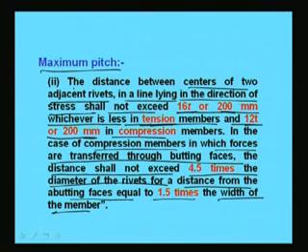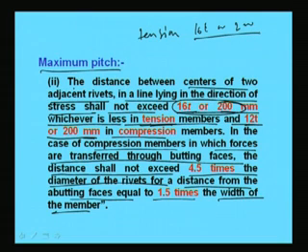So, what we have seen, in case of tension member, the maximum distance should be 16 T or 200 mm, whichever is less, and for compression this will be 12 T or 200, whichever is less. So, this criteria has to be remembered while designing the rivet joint.